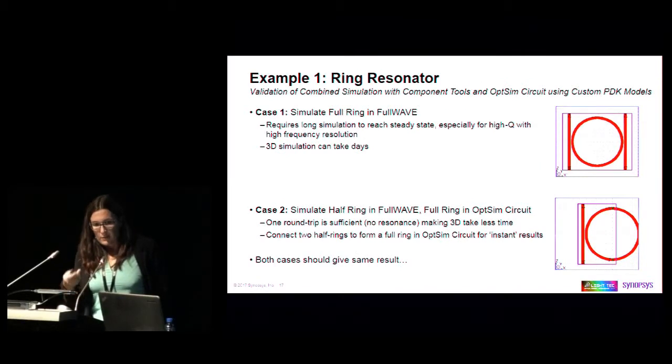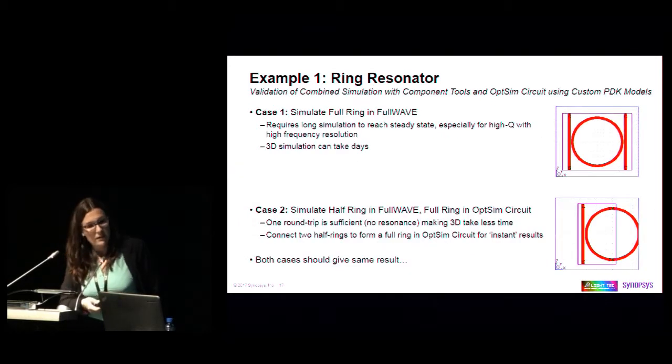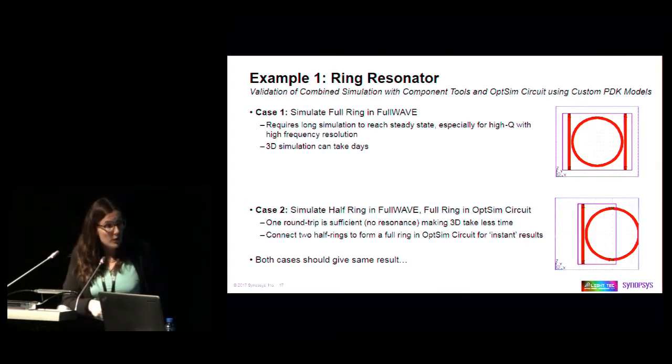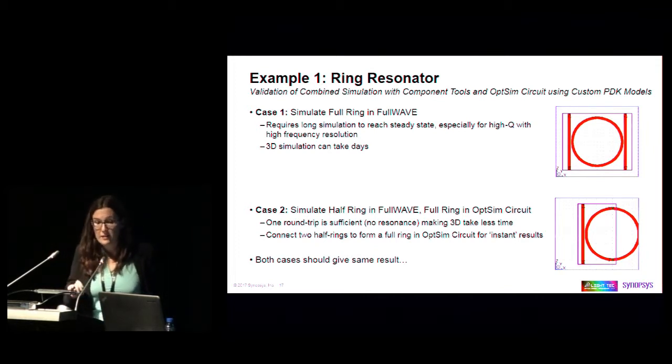But FDTD can be time and computer consuming, so we can simulate the full ring inside FDTD, or we can use all the advantages of the numerical methods developed inside RSoft to work on just half the domain. We can use a pulse launch field in order to generate the S matrix. And of course, we are expecting the same results from the two approaches.